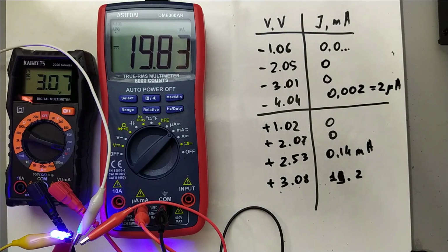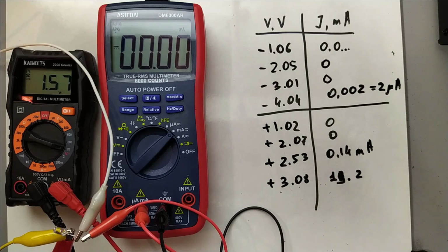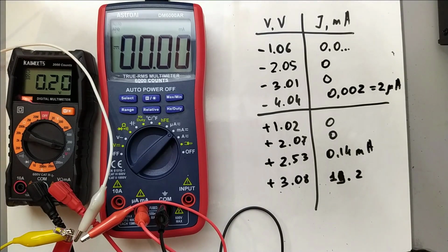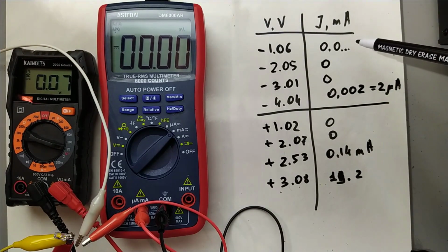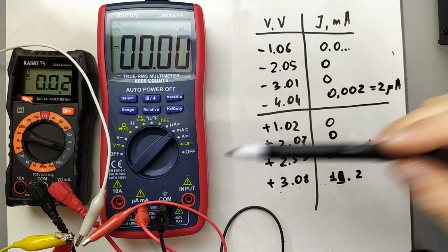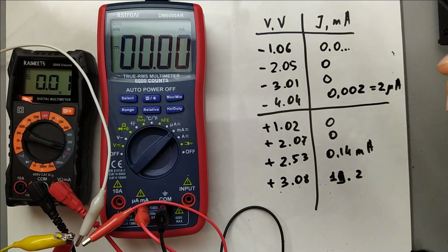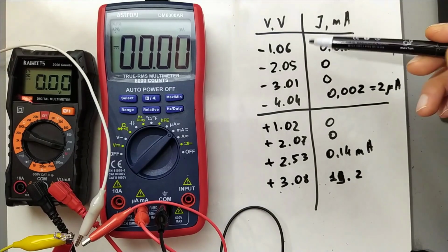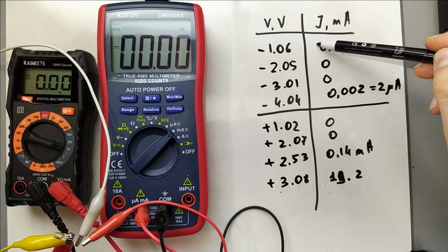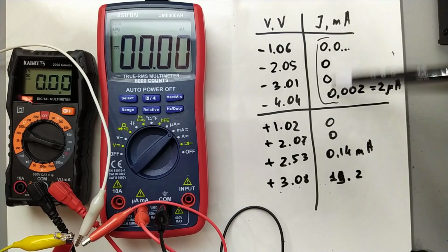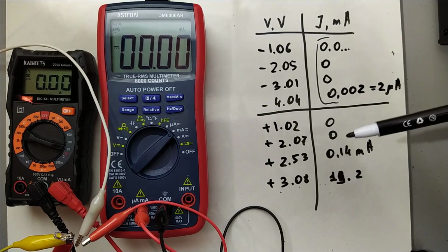So at this point we can reduce this, eliminate the forward bias, switch it to 0, and let us look here at our data. So we clearly see very asymmetric electrical conductivity of this device, asymmetric current voltage characteristic, polarity dependent. At reverse bias, starting from small to large reverse bias, pretty much nothing was changing. We had no current flowing through this LED.